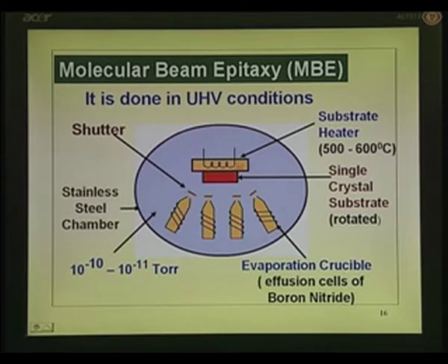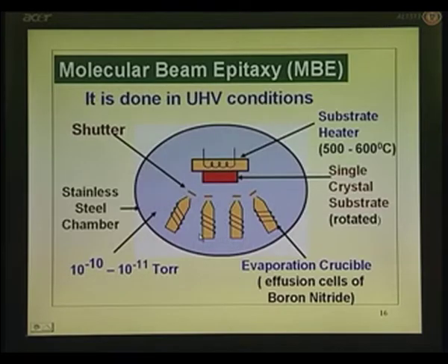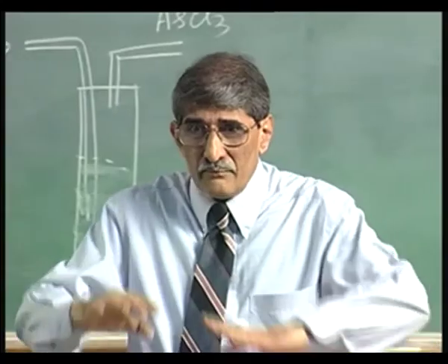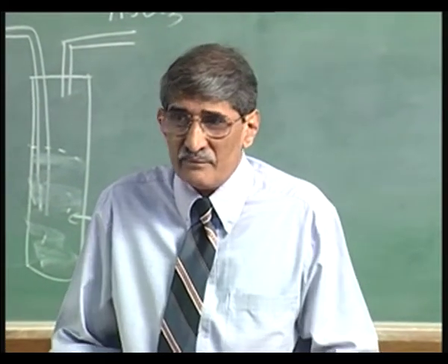So, what we are telling is very high vacuum is created, and that is done by using special pumps. I will not read out that. There are all sorts of pumps which are available which are oil free. Now, the most important thing that I want to point out is I just drew a circle or ellipse there. This chamber is made up of stainless steel, high quality stainless steel if you want to get down to those vacuum. And before deposition, you heat the chamber to high temperature to degas and pump down.